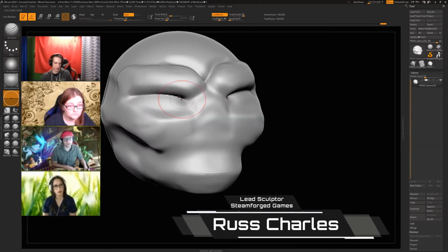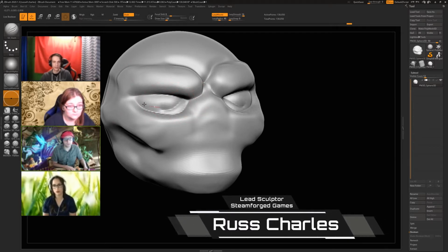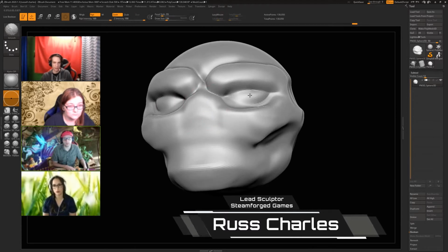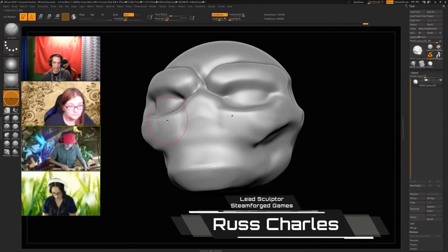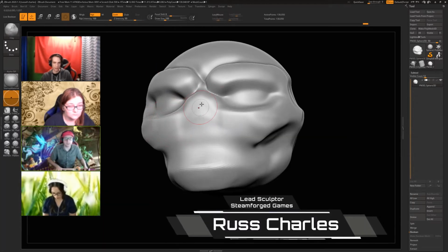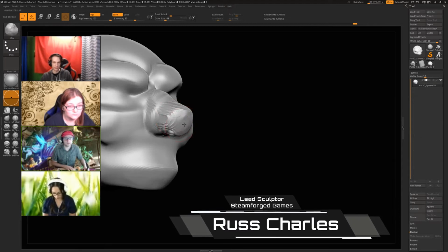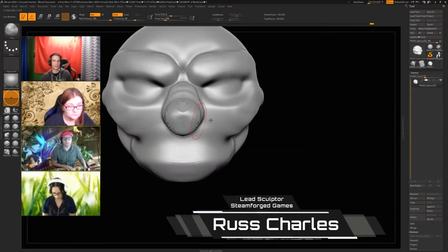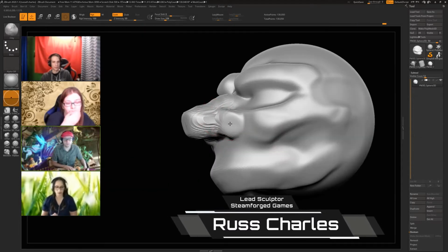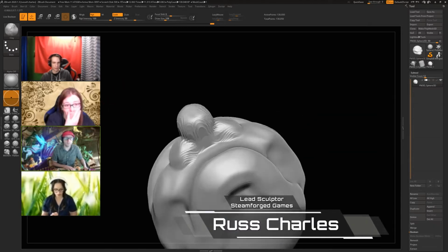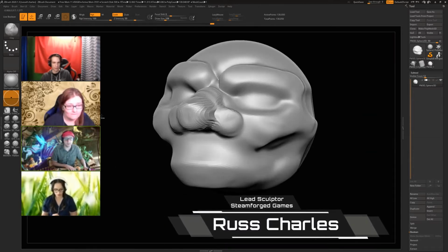So the answer to that is obviously more detail is always better. There is a limit. I generally work on the principle that anything on the surface of the model that is smaller than about 0.5 millimeter is probably not going to show up. And anything that's raised up off the surface of the model, about 1.5 millimeters is about your limit.